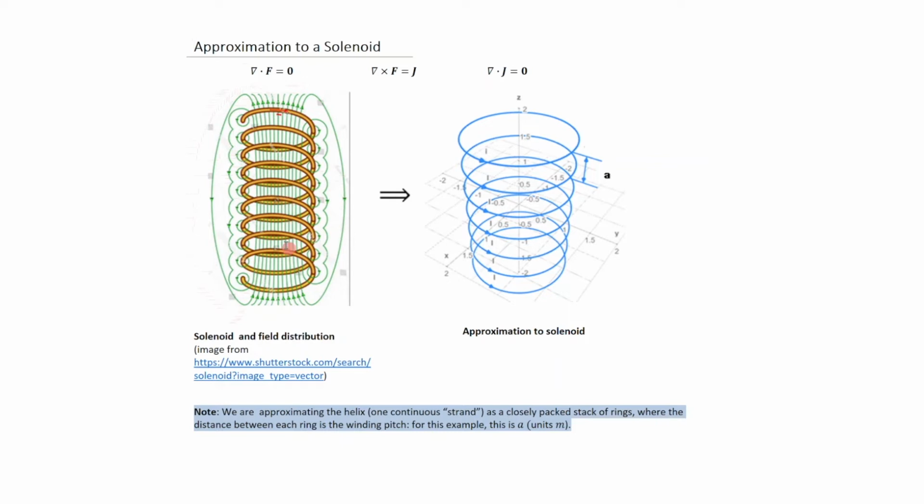And then also you'll notice that there's a periodicity here. So for example, if we look at a halfway point between two windings here and a halfway point between two windings here, that distance, of course, would be the pitch. You'll notice that the pattern repeats itself. So imagine going in this direction and then coming back in this direction. What you see in this direction is negated by anything you see in this direction. And so if we choose a contour which goes this side and then back on this side, where we basically preserve this periodicity, then this will make the contour integration very simple. So these are basically ground rules.